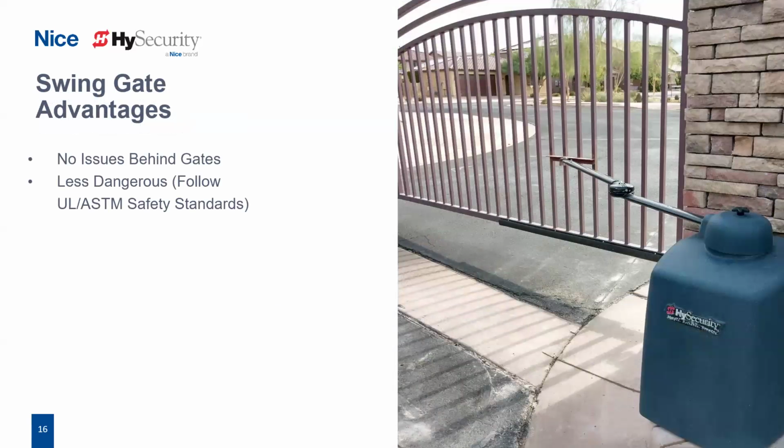Some advantages of the swing gate are that there are typically no clearance issues when opening these gates, and we typically get a full 90-degree open. And these typically tend to be less dangerous than slide gates. But again, we want to follow all of those UL 325 and ASTM safety standards.